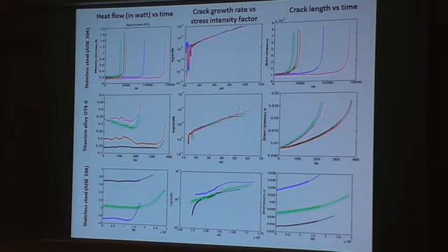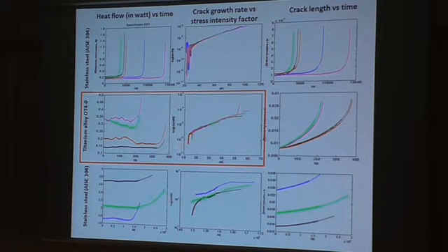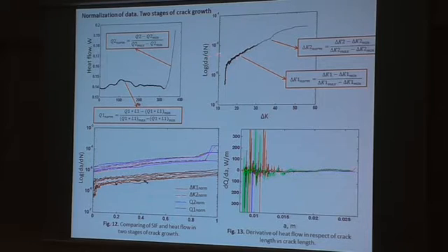If we consider this experimental data, this slide presents the idea. If we take this part of our process and put it on the standard Wöhler curve, it would be located in the beginning part of the Wöhler curve. For us, it was quite unusual, but under the ordinary Paris regime, we can observe two different regimes of heat dissipation and crack propagation. Up to now, it's unexplained for us, and we are looking into it.